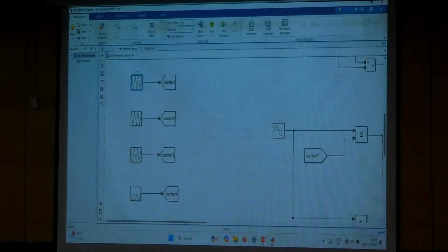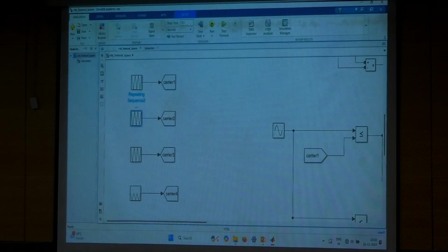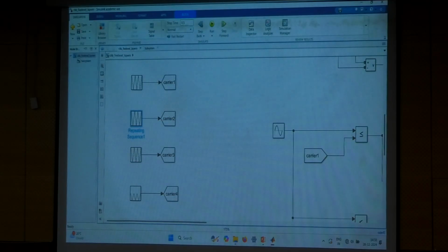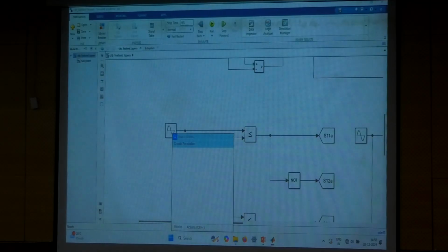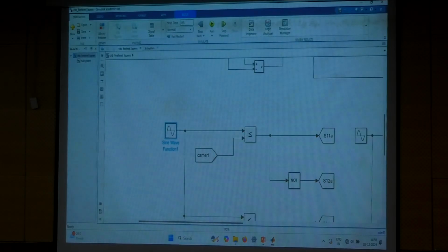Or else I will open this dialog box. So here, 1.5, 1, right, and this one 1.5, 0, 0.5 level shift PWM technique, right? I just put the carriers on the other side, that's all. And here I have a sinusoidal supply with some modulation index, some MA defined at the right.